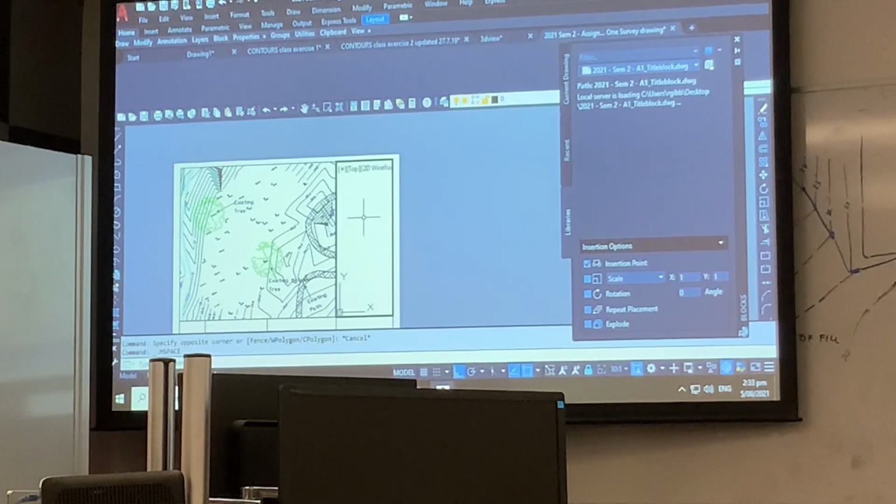Meanwhile, inside here, we're going to draw a rectangle. Now I want you to delete this rectangle when you're finished doing your notes and your other bits and pieces in here. Don't leave it there, that's sloppy drafting, but what I am doing is I now know that that is going to be in model space.